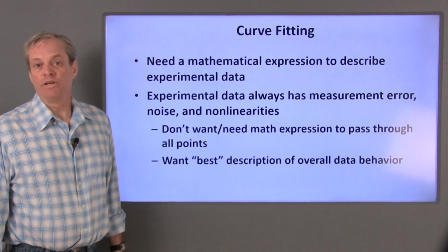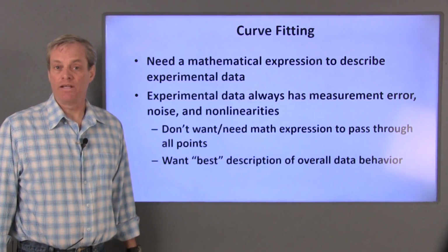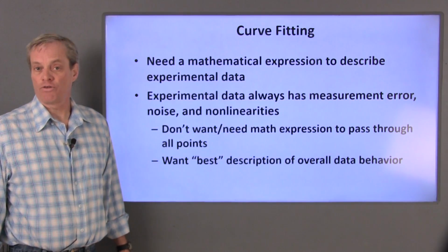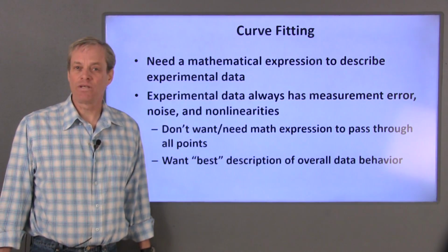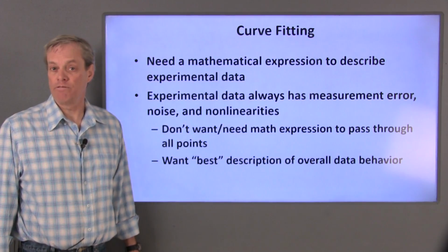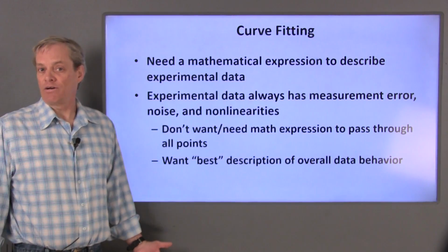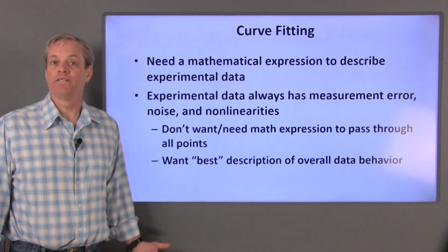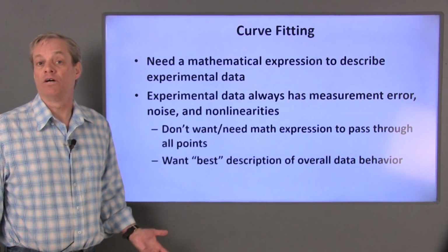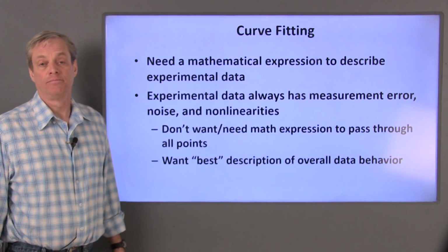For example, in a previous video, when we estimated the straight line equation governing the response of our thermistor from 2 points, the resulting equation didn't agree particularly well with the third data point we measured. It would probably be a better idea to use all 3 data points to generate a straight line equation that has the least overall error among all of the data points.